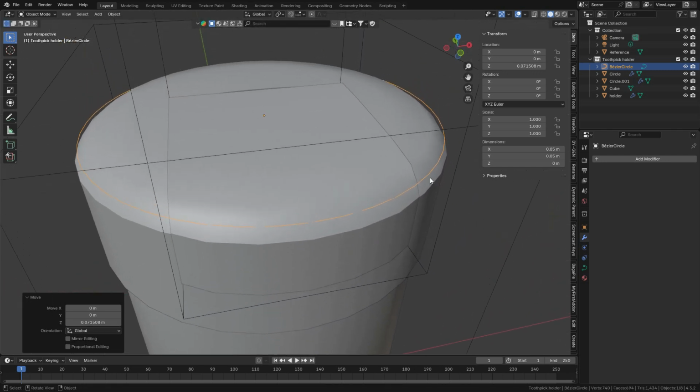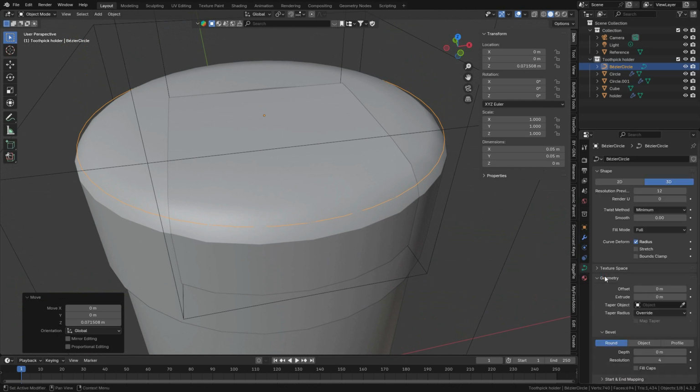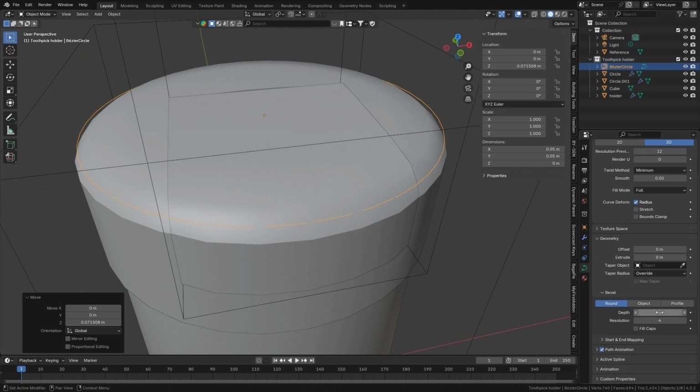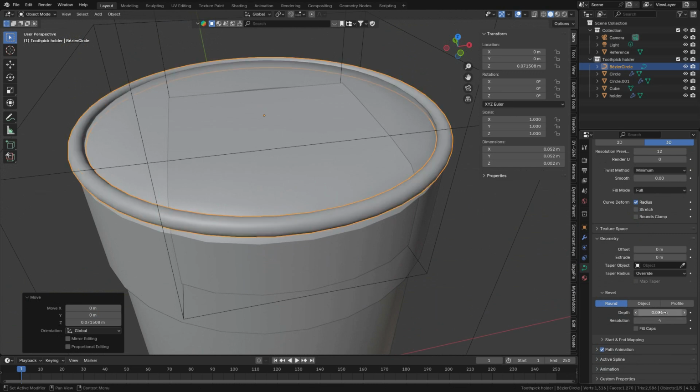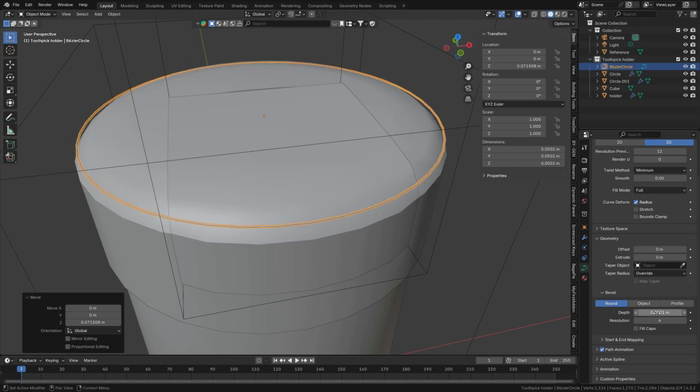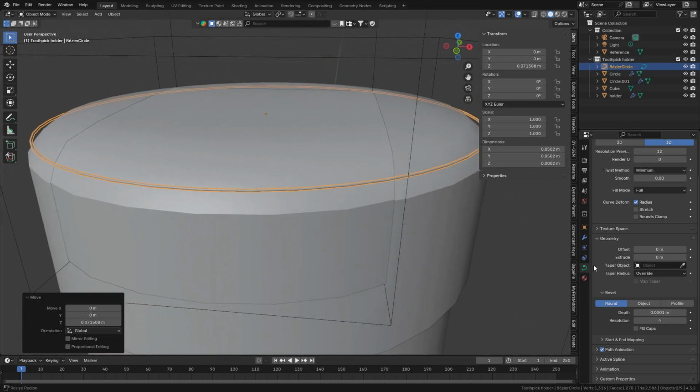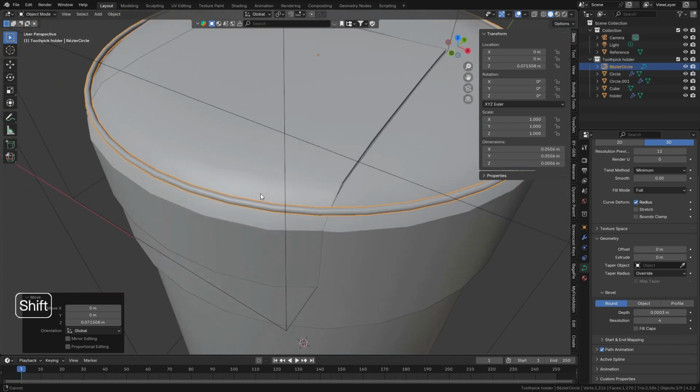What we want to do is make them round, so we'll go to the curve data properties here, go under geometry, go to round, and enter maybe a very small value like 0.001, which is still too big, maybe add an extra 0. Okay, I think that's just about it. Maybe make the one a 3. I think this should be okay.